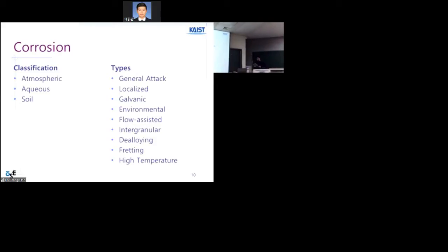Crevice corrosion frequently happens in a stagnant microenvironment, like beneath the gasket or flanges, and can be caused by acidity or toxic pollution. The third one is filiform. This happens when water breaches the coating of the metal, and then the corrosion spreads. This usually happens when there are flaws in the coatings of the metals.